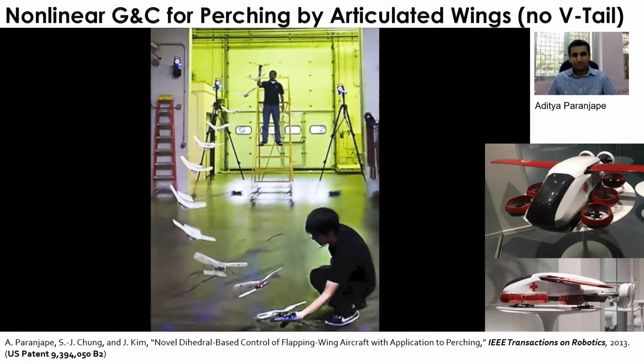And so this is basically a treadmill for aircraft, because we are demonstrating a fixed wing aircraft flying in a stationary fashion, like a hover, but it's not really using the rotorcraft to make it hover. It's using the wing-borne lift generated from the airflow coming from this fan array. So it's almost like a wind-based treadmill, and we can generate disturbance in addition to the main flow speed, where we can test our adaptive control method. This method shows that it can outperform conventional PID control.